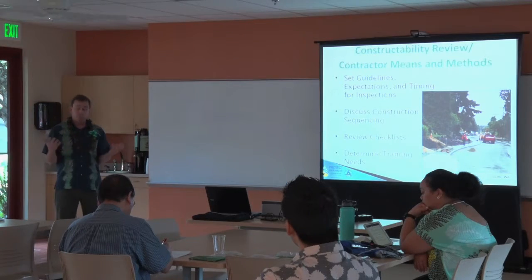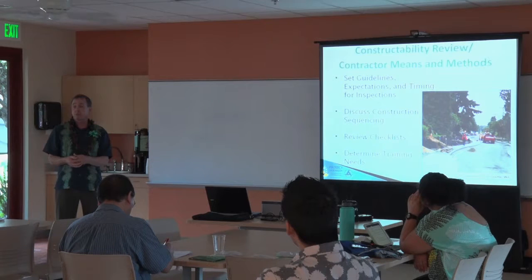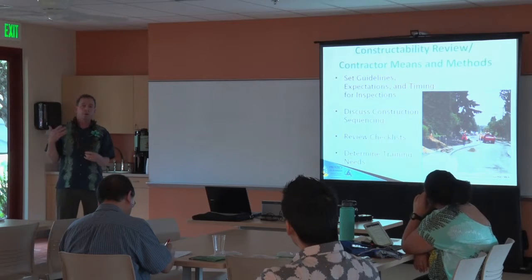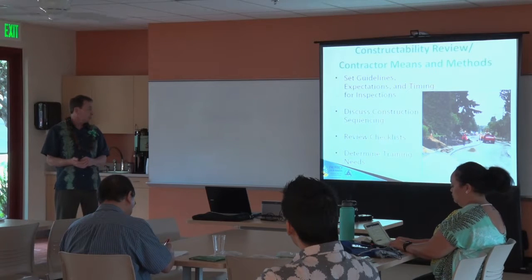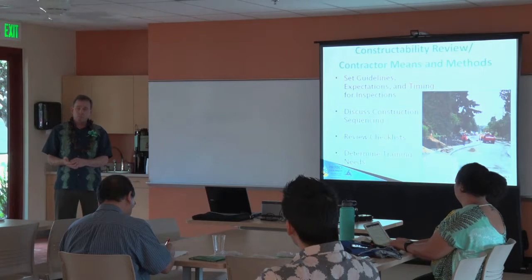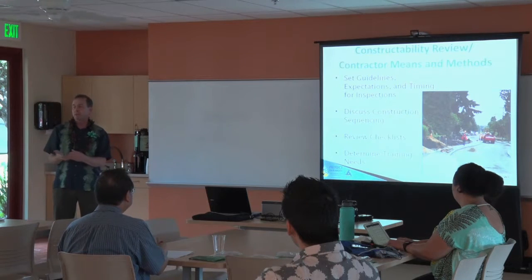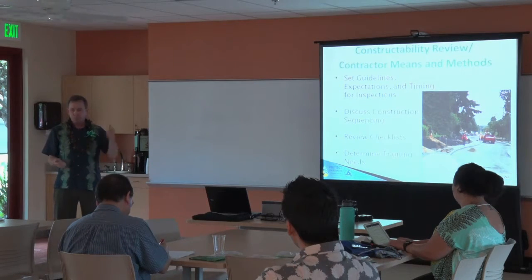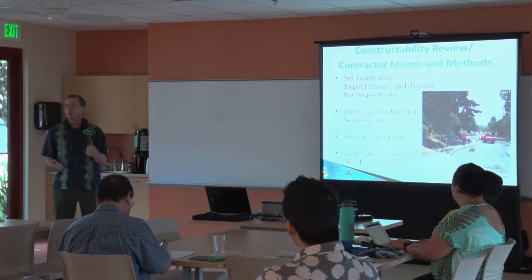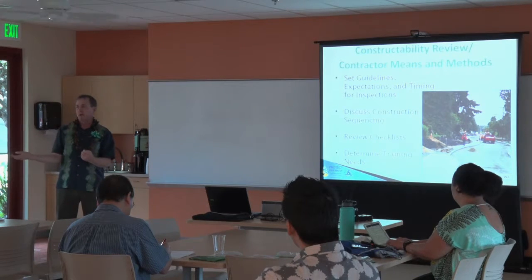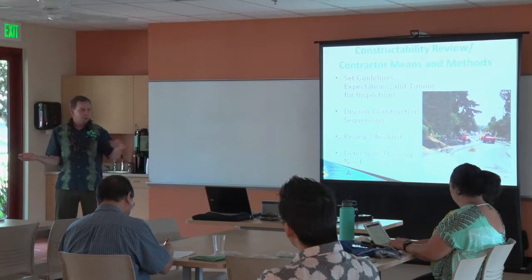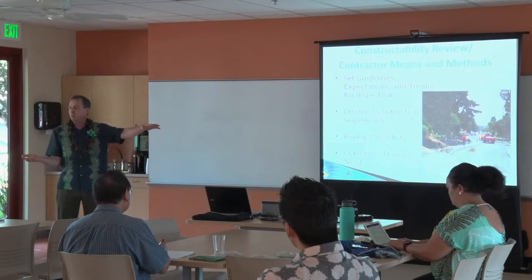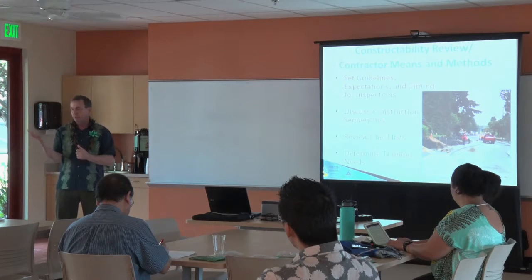And I bring up contractors' means and methods because obviously we don't want to tell the contractor how to do the job. But for some of this stuff we're going to talk about, we need to educate the contractors on the importance, or maybe it's holding a hammer over their head to remind them that we don't want to flood our newly constructed LID feature with sediment from the road work that we're doing over here before we actually put it into use, because we plug it up.